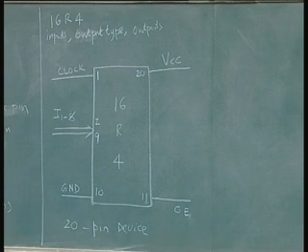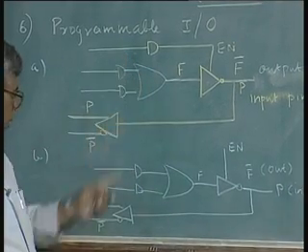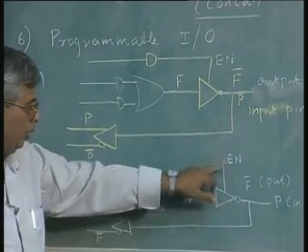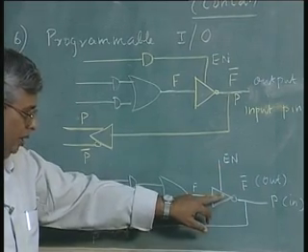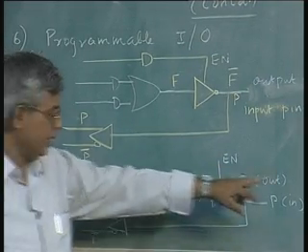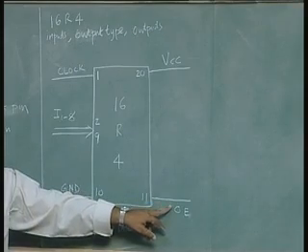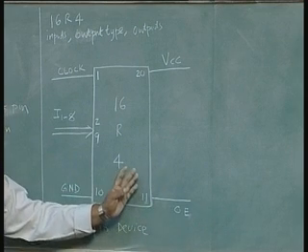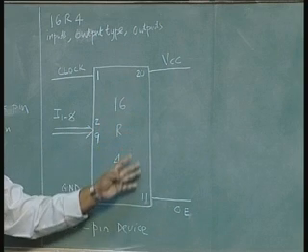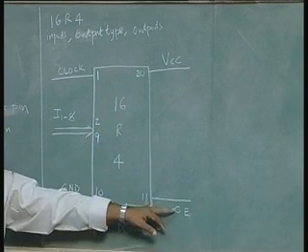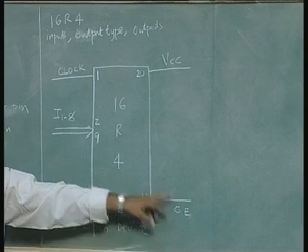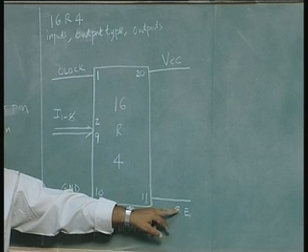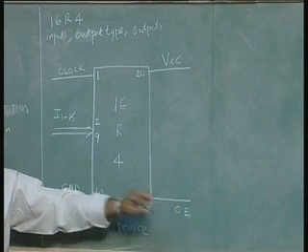I said one output enable can come either from a combination logic block or from a simple pin. This pin will provide the enable for the buffer. In this case, this is a simple pin enabled buffer. So, this output enable enables all the buffers which have the programmed IO feature. All the programmed IO types are enabled or disabled by this OE. So, we need one pin, similar to the clock, which caters to all the programmed IO pins.